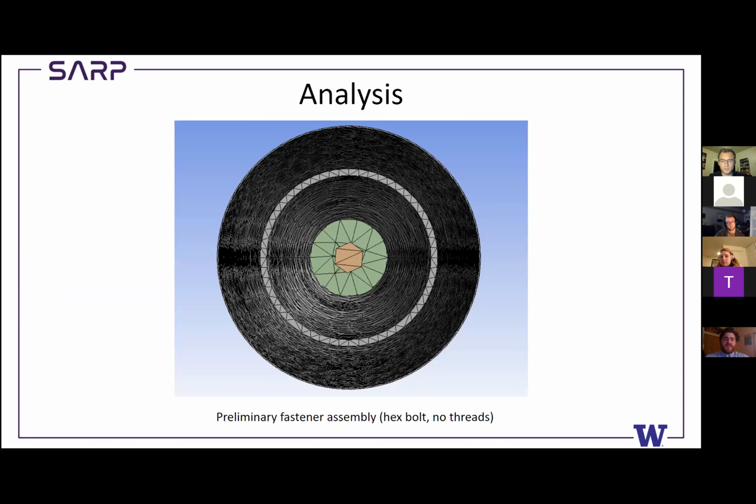Here, this is looking at the bottom of the nose cone. Now, if you look at the circumference, that very thin face right there, that's where we put our fixed support. And if you look down the middle there, you can see a hex bolt. It's a simplified version of our eye bolt. We applied the force on that face.